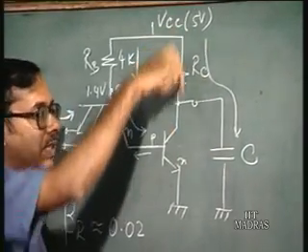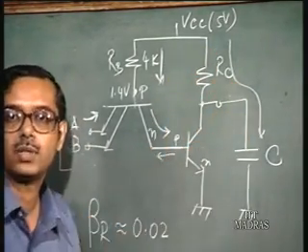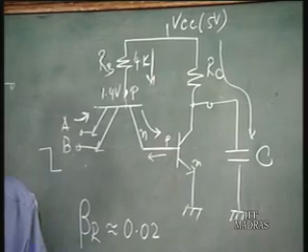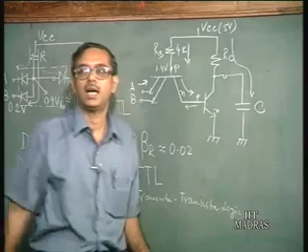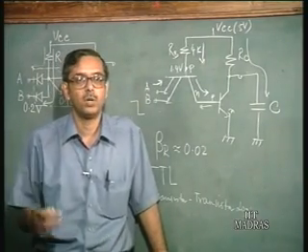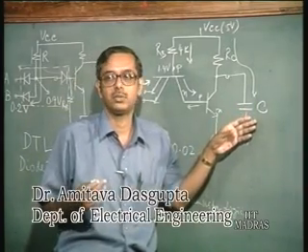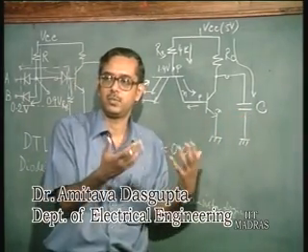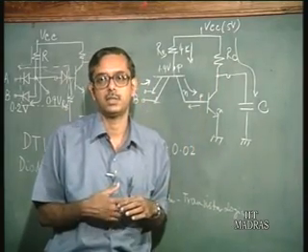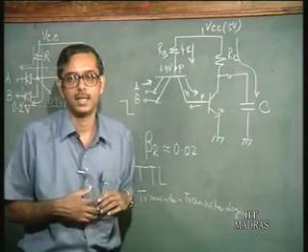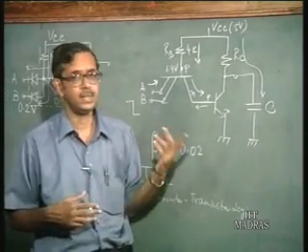Normally when the transistor is in saturation, the current flows into the transistor, but when the transistor has gone off, the current flows into the capacitance, charging it. And the delay of this process is given by the RC time constant, correct. Now, in order to reduce the RC time constant, of course you cannot reduce C because that is the load. For a particular load, you have to reduce the collector resistance. But if you reduce the collector resistance, there is some problem.